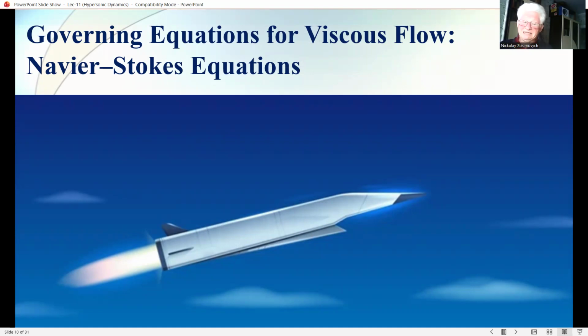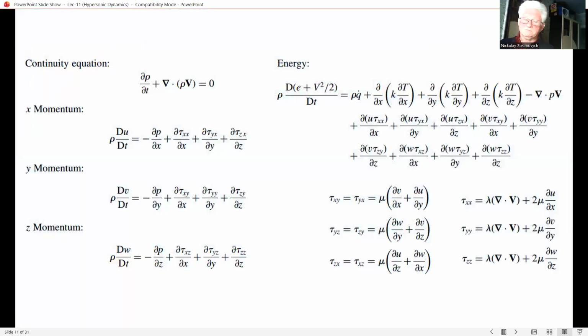Another way of stating this is that the Euler equations are the limiting form of the general viscous flow equations in the limit of infinite Reynolds number. Indeed, it is frequently convenient to think of inviscid flow as a flow that results from the Reynolds number approaching infinity.